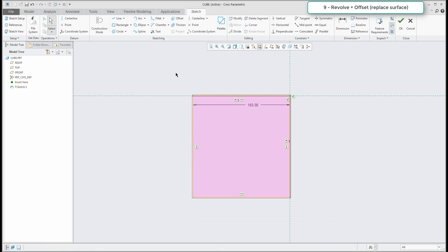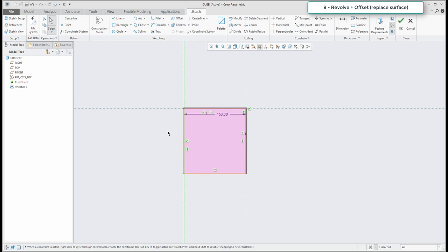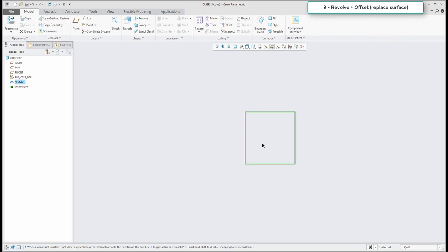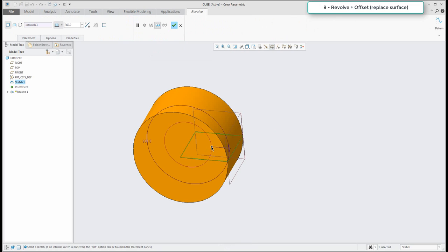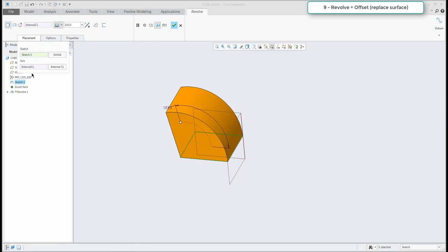And what we can do here, I will create directly in the sketch the center line. So you know that if the sketch includes a center line, and if you now use the revolve feature, the system will automatically create the feature based on the internal center line. That's good. I don't want to use the angle 360 degree. I would like to use only 90 degree.